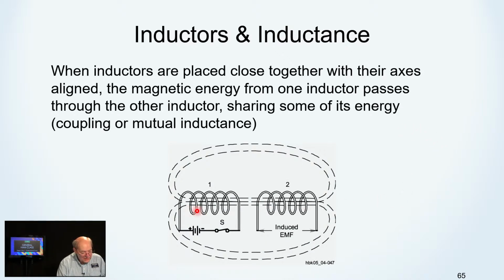Now, these are two inductors wound in a straight line, which are also called solenoidal inductors. If they're placed end on end like this, they can share a magnetic field. They actually couple energy from one to another. That can be an attractive and beneficial situation if you're doing it on purpose. If you didn't mean to do it, and you're coupling energy from one part of your circuit to another on a circuit board, that could have results that would be very detrimental.